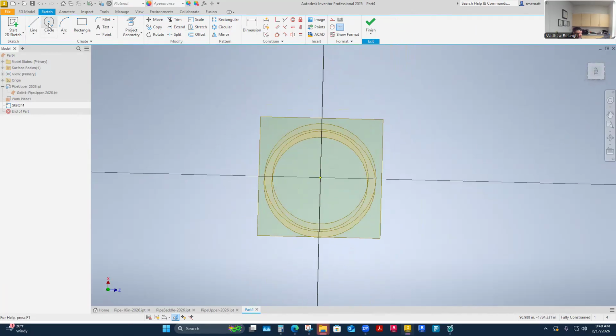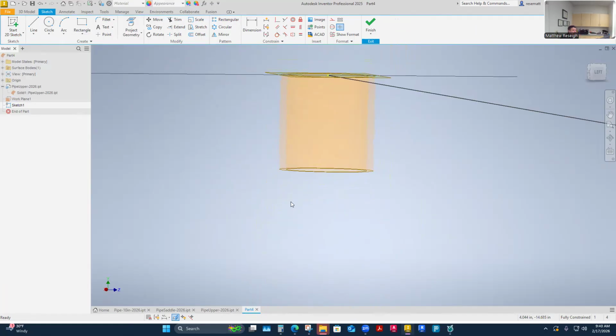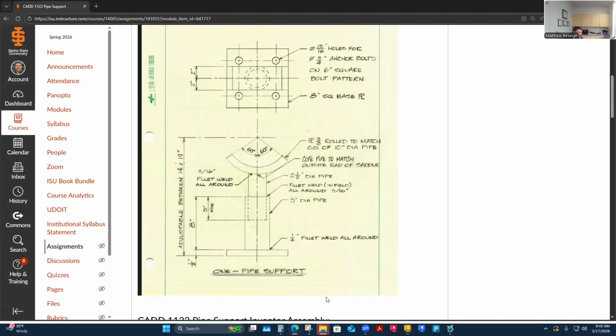And then I offset it 3 inches from the square bottom edge because I ended up having to do a -3 just based off how it was establishing my plane. Yours might be a positive value. I think it can vary on your selections. Mine ended up needing to be a negative value, but I established a plane from the bottom of this 3 inches up here.